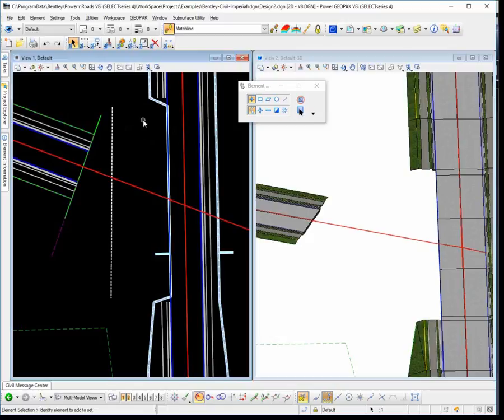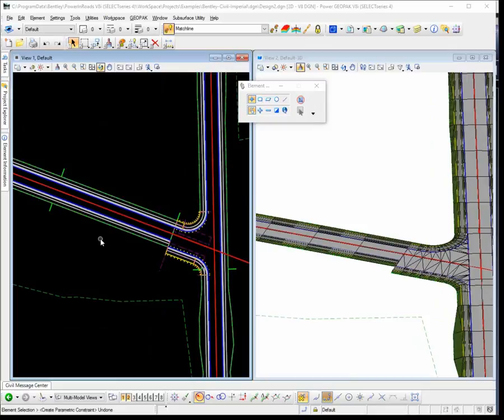And there are other videos out there that show how to place a civil cell and how to add the key stations at the end of the fill, etc. The point of this video is to show you that there are better ways to have that not draw beyond the edge of the pavement by using this approach of using component display rules with parent-child relationships on your templates seeking match line. Another tip is to take advantage of using parametric constraints over point controls.